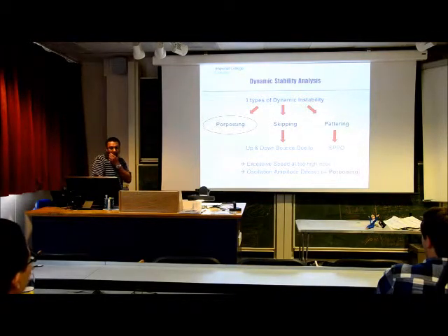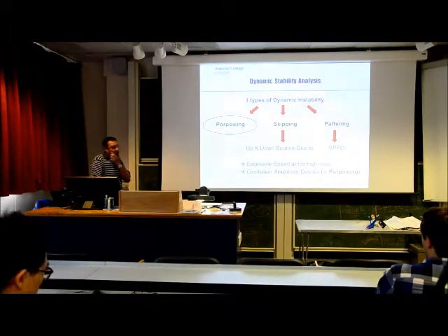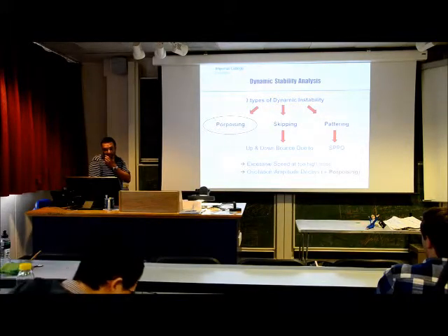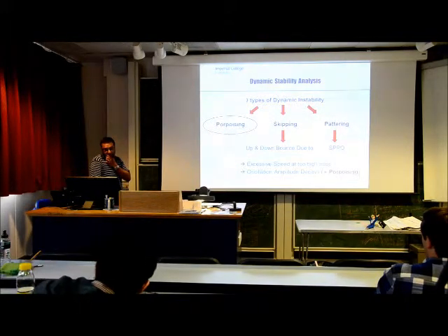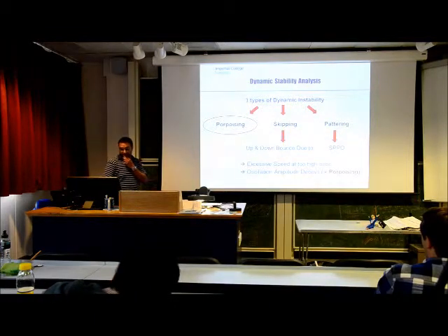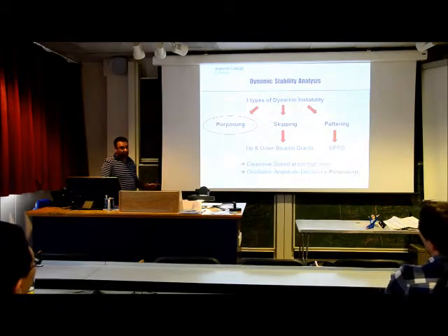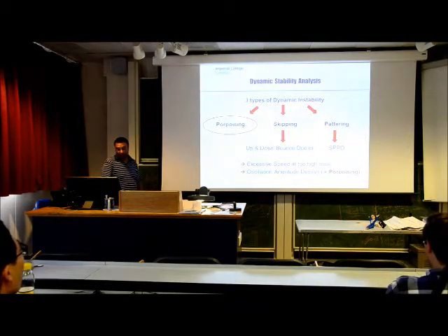In addition to porpoising, which was mentioned last week, there are two other dynamic instabilities occurring at the surface of water, essentially skipping and battering. Skipping depends on the speed we are approaching with and the position of the nose relative to the horizontal.